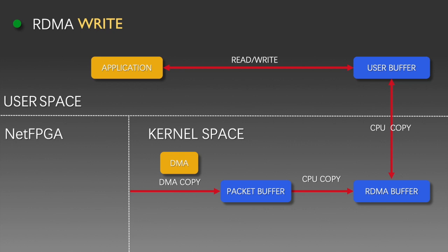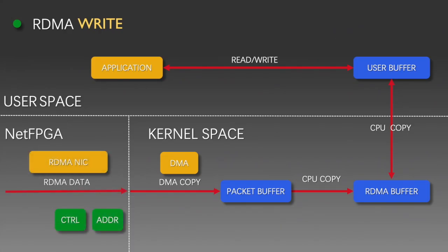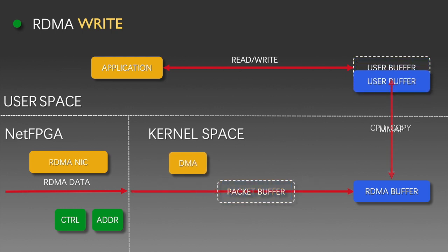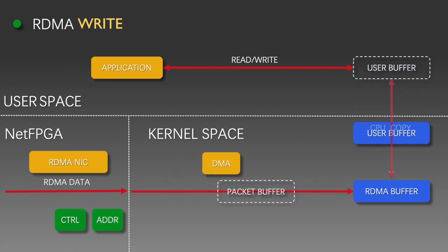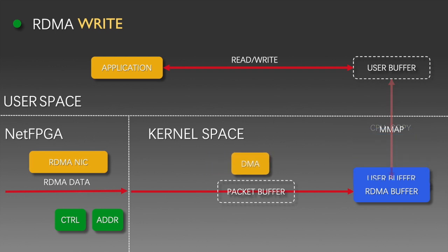After the RDMA packet is sent, our network processor on FPGA will decode the packet and recognize that it is an RDMA packet. It will then trigger a specific routine and modify two hardware registers to tell which command it is and what address the packet is trying to write to. If it is an RDMA write packet, instead of going through all the unnecessary memory copies and data queues, our customized driver will read from those registers and bypass the operating system and directly deliver the content to the user application.